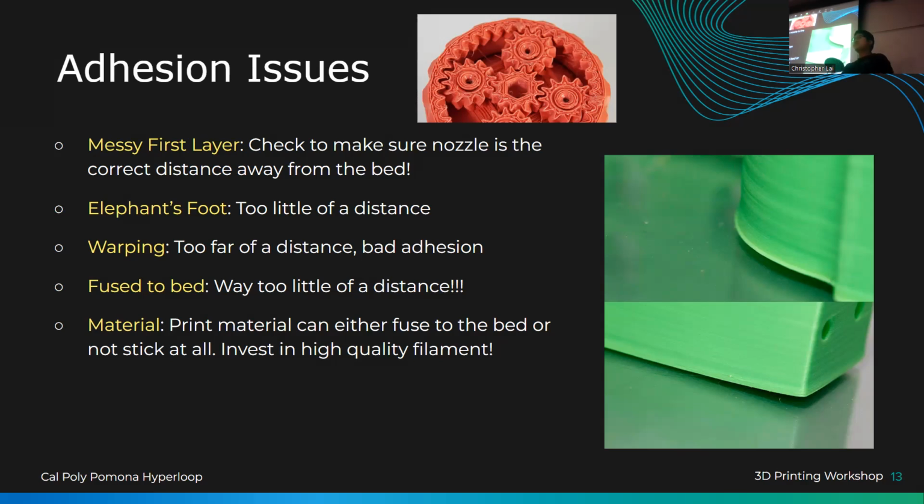All of this is just to show you how many things can go wrong with 3D printing. A lot of people have hot boxes or dry boxes that they put their old filament in to try to remove the moisture, and it works. Some people even keep the filament in the hot box while it's printing. Yeah, that's what I do. I have one system with a little hot box as a separate unit.